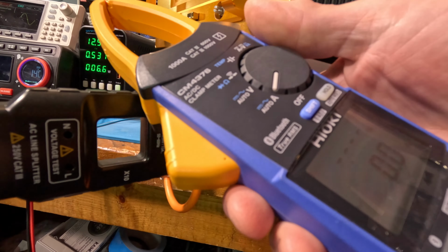All right, guys, so you saw the setup, okay? You probably guessed it, but yeah, this little MIG-SIG current probe, pretty cool. It just has this little magnet thing that goes pop in there, and I just take it around, and these things are really handy to go on a panel or whatever to measure current. And for a low frequency switcher, they're working great, right? Even though this thing's designed to look at high currents, it's done pretty good down here at the lower current range.